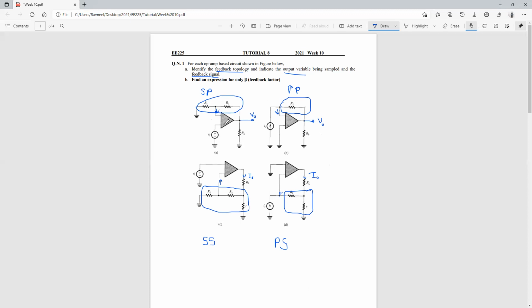How do you identify the alpha circuit, right? That's the important part. You can see this particular circuit. So how do you identify the alpha circuit? For your input part, you break it from the output and you ground it. Whatever connections you have to your output, just forget about the RL circuit. Whatever connection you have to your output, you break it and you ground it, right? And for your output resistance, whatever connections you have to your input, you break it and ground it, right?